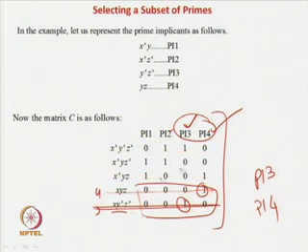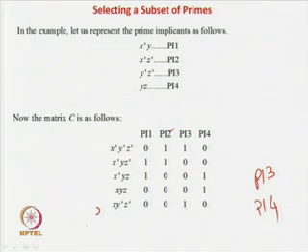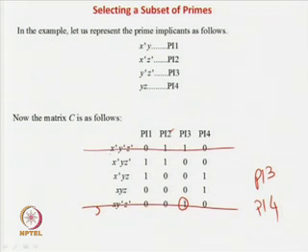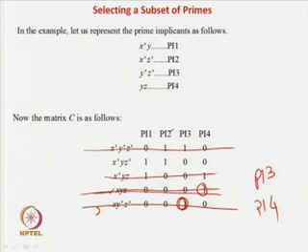So, let us quickly recap what we have seen, since we are discussing slowly. You see this is a singleton. You first have to find the singleton elements. That means, to cover this one Pi3 has to be taken. If you take Pi3, this one is covered, and obviously this one is also covered because it contains this one. Now, this one also, by this row, is a singleton. To cover this element you have to take Pi4, and then this one is covered. Obviously this was also a 1, so it gets covered by default, by virtue of selecting Pi4.